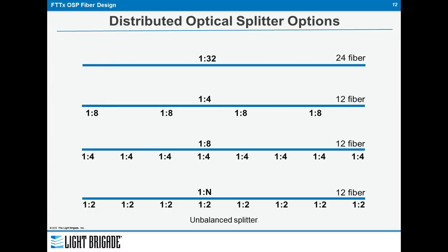For example, 100% of the light comes in, 90% continues on, and 10% is dropped to your customer because it's very close to the transmitter. That has some inherent disadvantages, because when you start adding customers that are downstream, you have to design it so that you actually know what the incoming power requirement is, as well as if you have to cut the fiber to drop that customer or to splice them into the network.